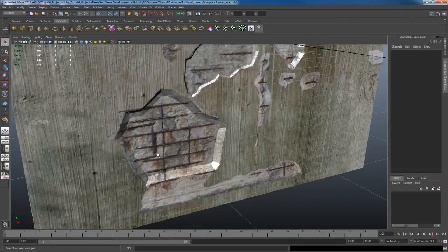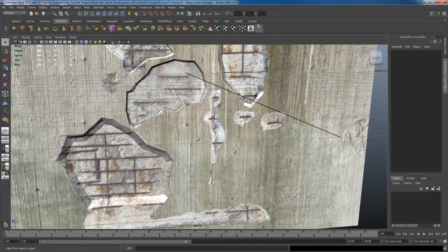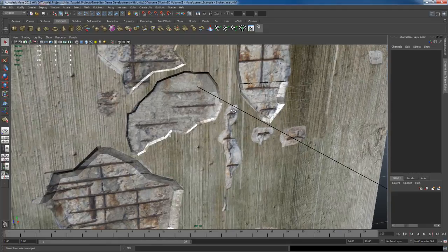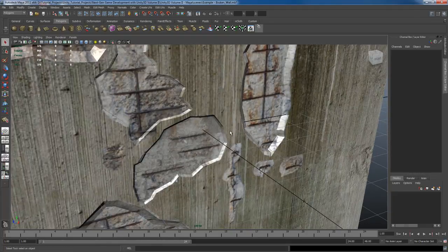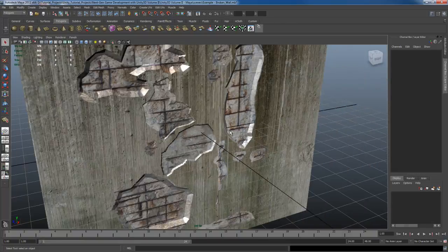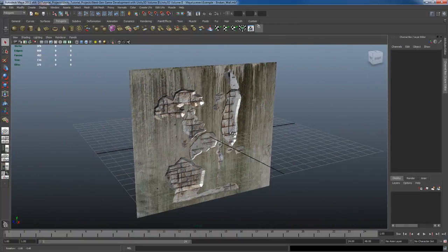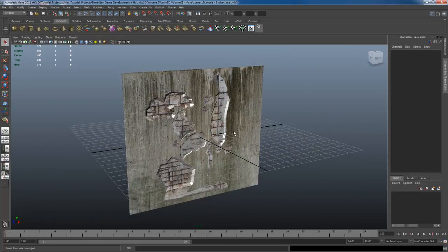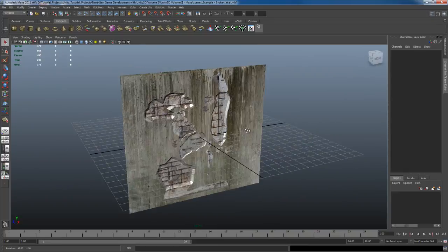I just modeled in this big main area. And also you notice that there's no modeling for these small cracks over here, simply because we do have triangle limits and limitations. We can't waste too many triangles on stuff that is not important, so we need to spend our triangles on stuff that is important. So you can see how I did this here.